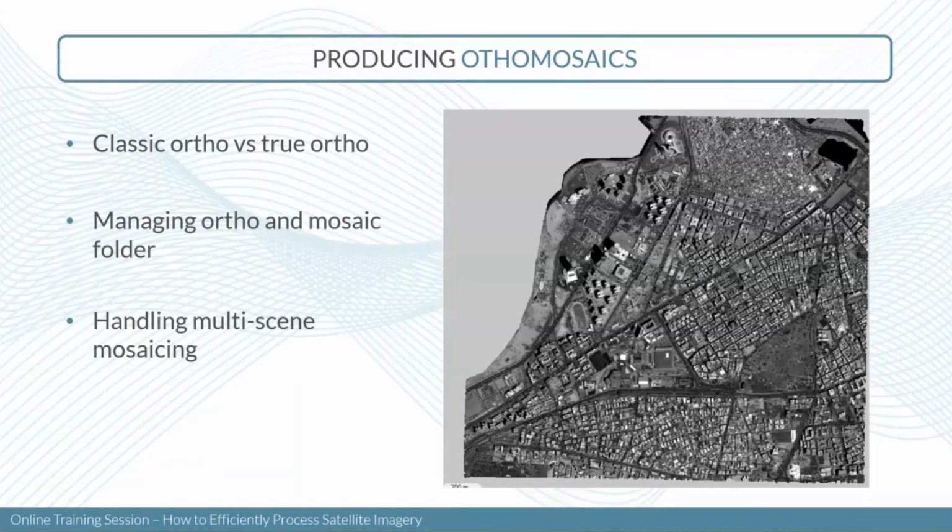We usually recommend doing the ortho directly from the terrain model, because it gives much nicer results. But you can also perform a true ortho if it's your need. From your true ortho, you can also input some 3D break lines. So if you have, let's say, building roofs that are already vectorized, you can use them as constraints during the ortho rectification.